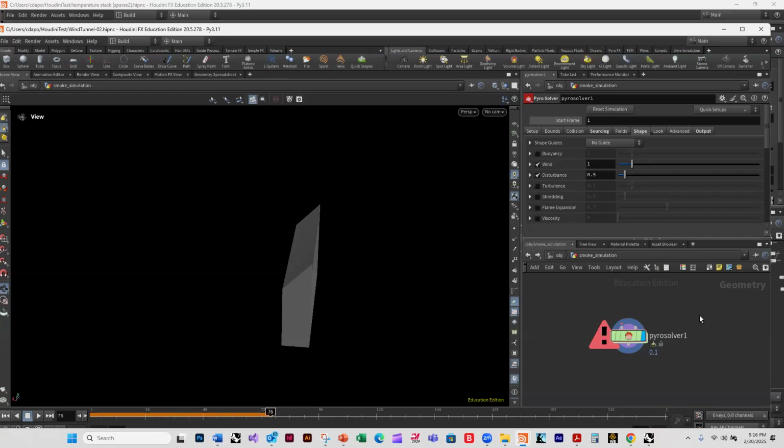In order to send in the sources, all that stuff we were doing with the attribute VOP and everything is for the things I showed you with the torus that have points on them. We're not working with points anymore, we're working with voxels, right? So in simulation we solve voxels. So we need to make what Houdini calls volumes or VDBs.